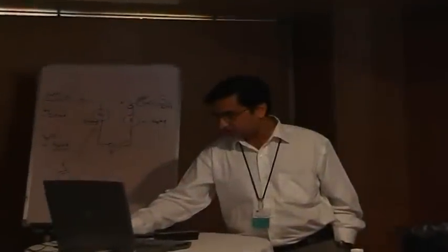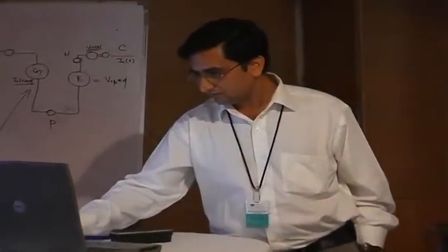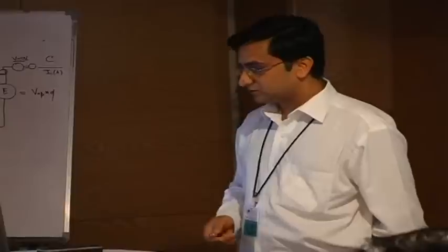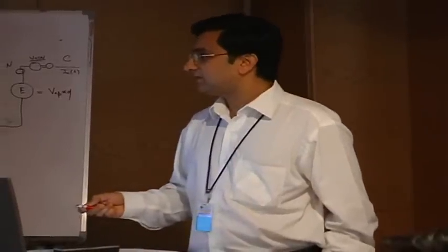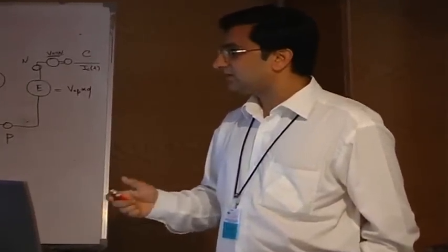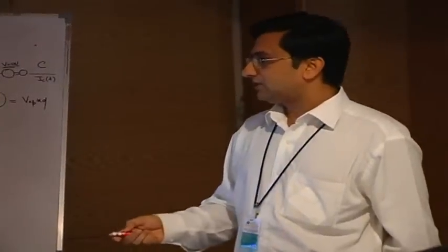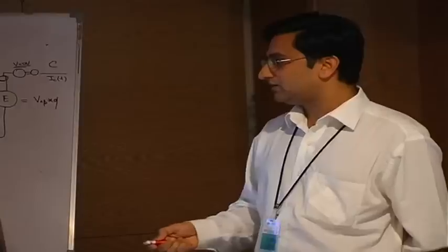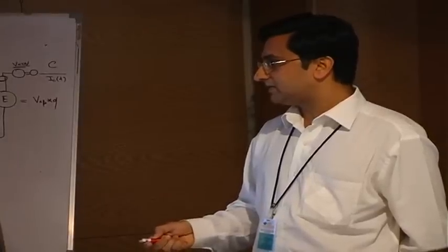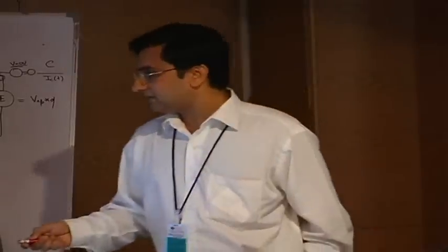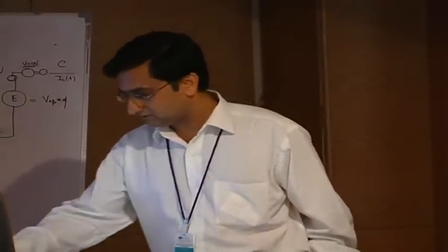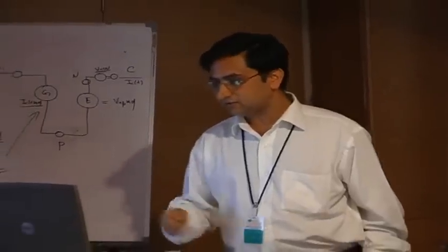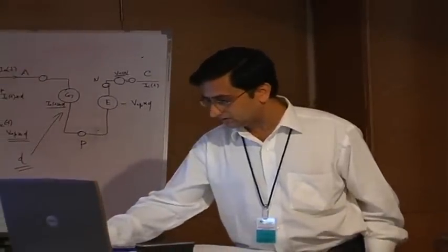Then I come to the FE domain. Here we will be talking about static, quasi-static and transient solutions. We can simulate isotropic and anisotropic materials. Of course, we can do optimization here. It has a very strong co-simulation with Simplorer. It has a direct link with RMxprt, the analytical tool. And yes, we can also take it to stress and thermal analysis. So these are the solvers that it has, and it can solve various problems in this FE domain.